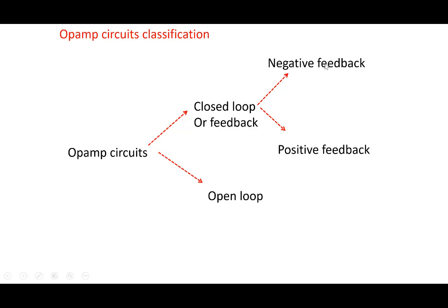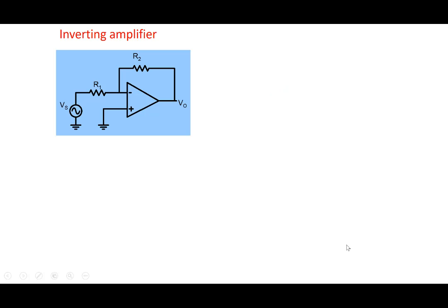They're often stable, and one can do a wide variety of things with feeding it in the negative direction. When you put positive feedback, the circuit tends to become unstable, and we often use such circuits for making oscillators, where you want the circuit to oscillate between two stable states. So most op-amp circuits will employ negative feedback, and that's where we will concentrate our attention here.